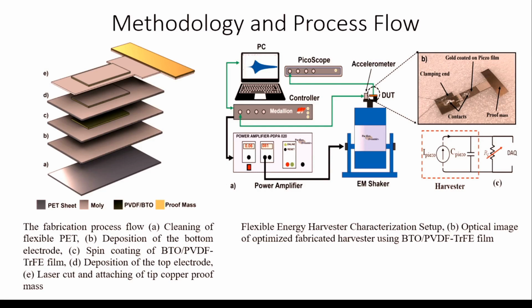Below, you can see the fabricated piezoelectric energy harvester using the PVDF and BTO film, and on the bottom you can see the equivalent circuit. It has a piezo current source connected in parallel with the capacitor of the piezo sandwich layer, and RL is the load which we connected to measure the power or voltage across the generated cantilever harvester.